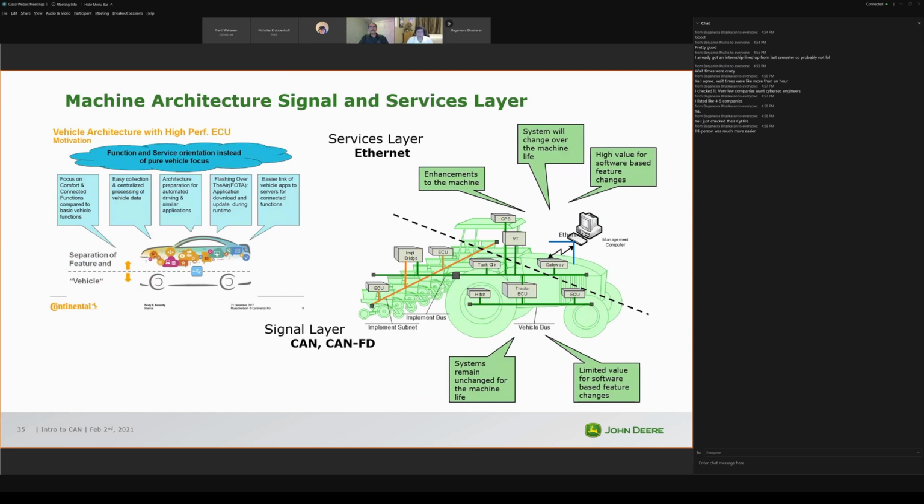But when you look at Ethernet, putting Ethernet connectors on a machine to last the vibration, to last the life, to go through temperature cycles, because the technology we put on all cars and all off-road machines has to survive and work at minus 40 up to 40 and even up to like 125, talking about temperature in C. So really high temperature depending upon where it's mounted. And so getting a technology and connector system that will survive that becomes really expensive.